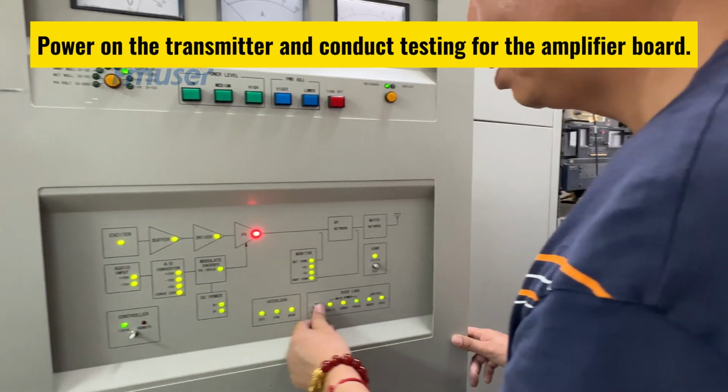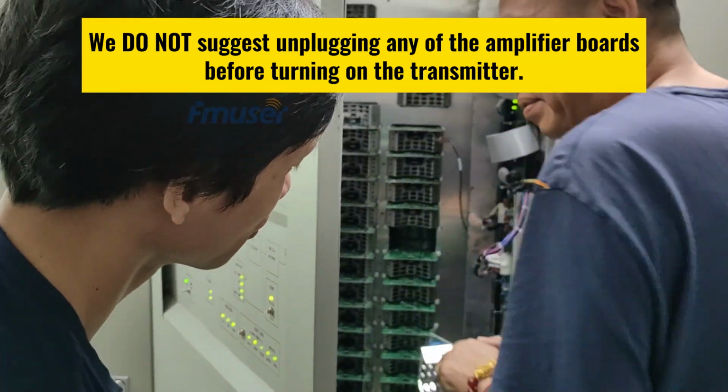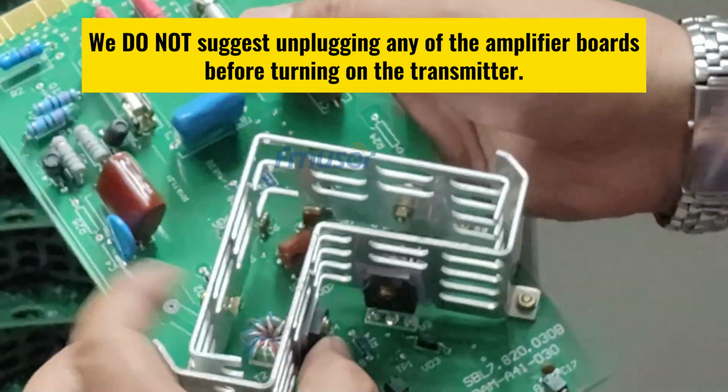Afterward, power on the transmitter and conduct proper testing. It is worth emphasizing that it is highly recommended not to unplug any of the 48 power amplifier boards before turning on the transmitter. Doing so poses significant risks and can be extremely hazardous for the transmitter operation.